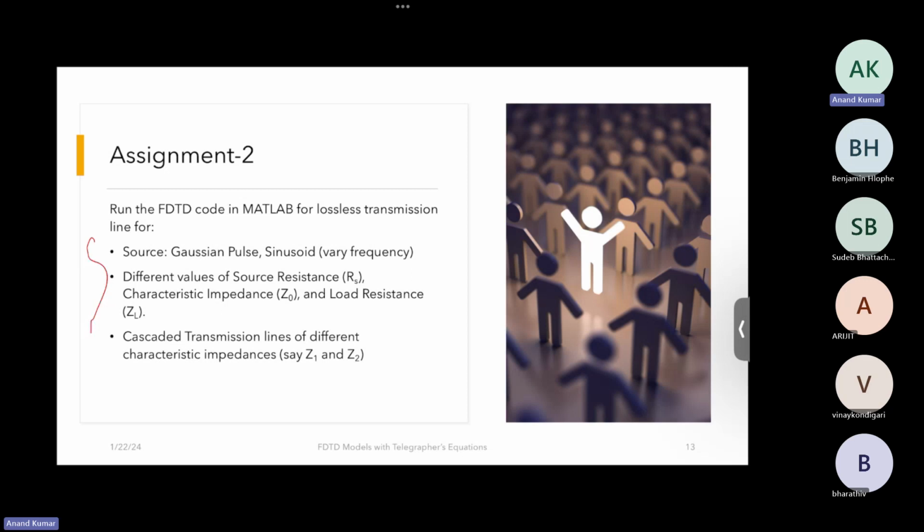Okay, so for the last question, which I could follow: in the sine modulated Gaussian pulse, you could only see a Gaussian pulse and no sine modulation, right? Yes. So for that, one reason could be that the sine wave's frequency was much smaller than the Gaussian envelope. So if you increase the frequency, you might start seeing some sinusoidal pulse inside the Gaussian envelope. Maybe you can try changing the frequencies. I'll also see if there is an issue with that.